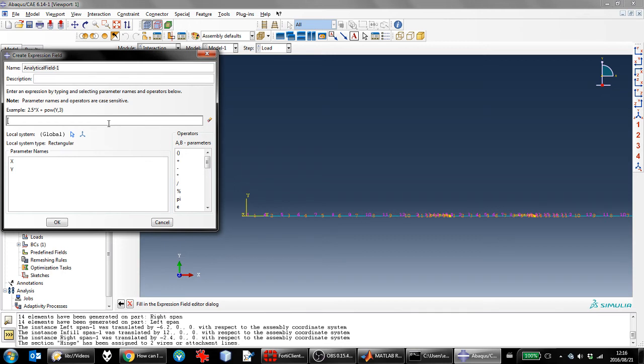So in this case, you have to work out the slope of the line, which will obviously be the load over the x distance. I'm just going to give it a value here now. So let's say that's 10,000, or 10 kilonewtons per meter times x, where x is obviously our distance in meters. I'm not actually interested in what the final value comes out to in this case.